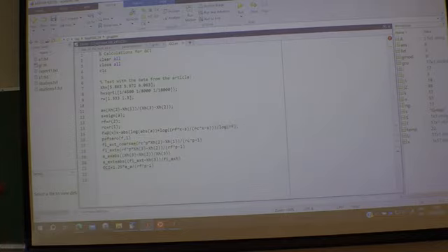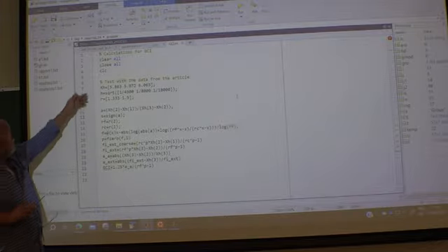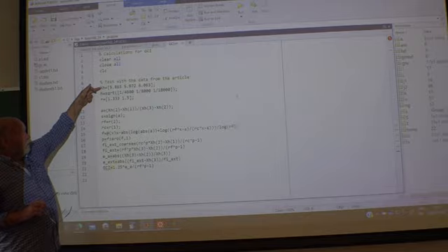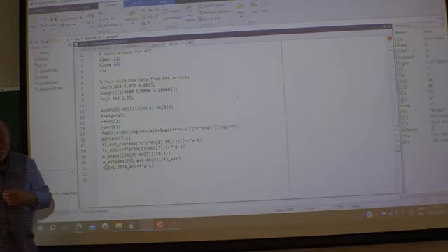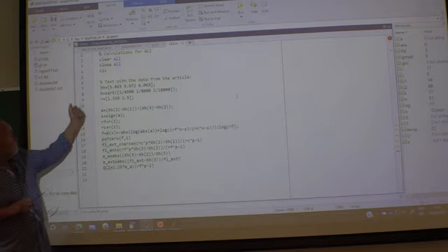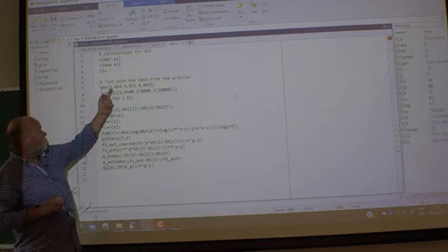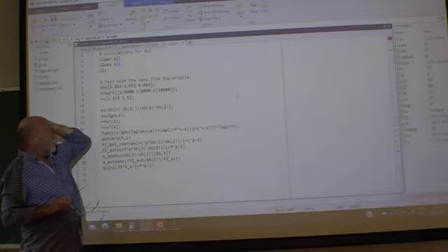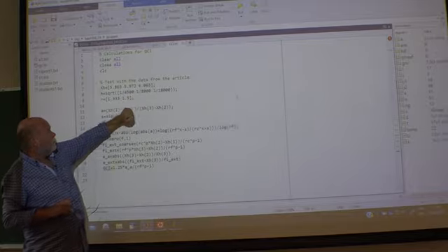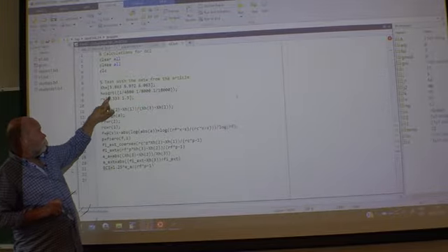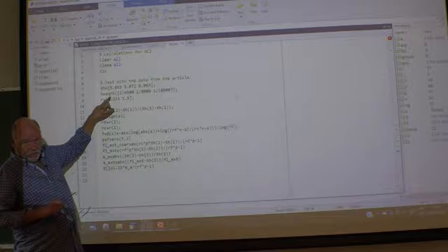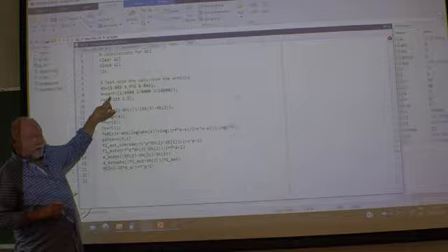So this one is just a cute little MATLAB script. And here I've just taken the numbers from this article. And here also you can see I did the dirty trick. These were the monitor values that they displayed with finer and finer mesh. Here was the number of cells. But first of all, square root, because it's a 2-dimensional thing. If it was 3D, you would have to take a cubic root here.